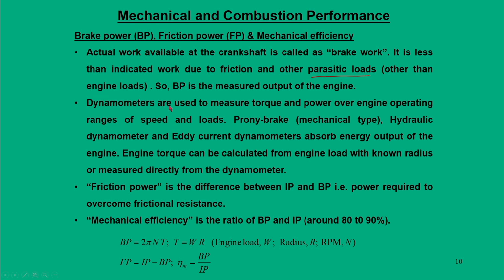So, what are the typical dynamometers? These dynamometers are called Prony brake, which is a mechanical type. It can be a hydraulic dynamometer, another kind could be eddy current dynamometer, that is electrical, which is mostly used, and they absorb the energy output of the engines. I am not going into details of all these, because these are different topics as far as IC engines are concerned, but in our philosophy we will just look into how we measure the torque and power output from the dynamometer and try to correlate with our engine operating parameters.